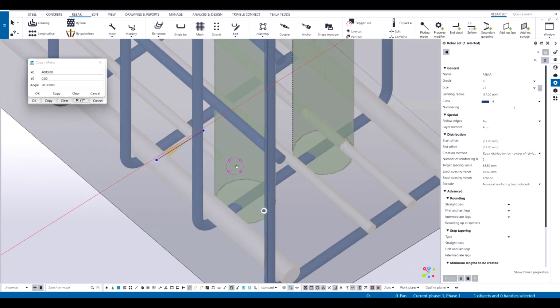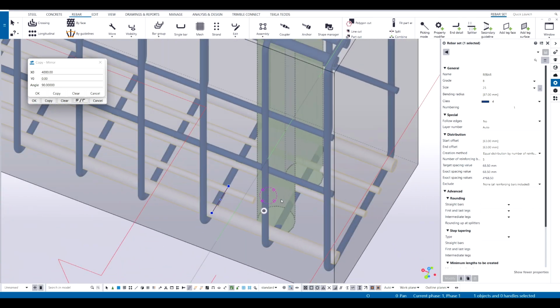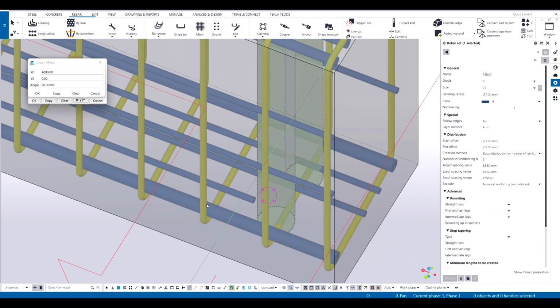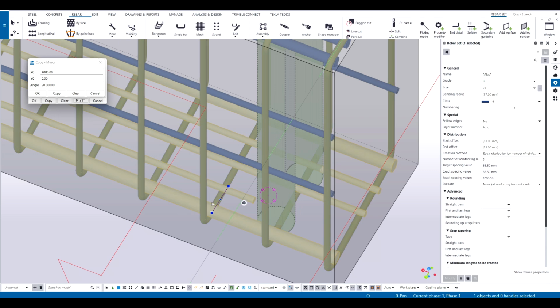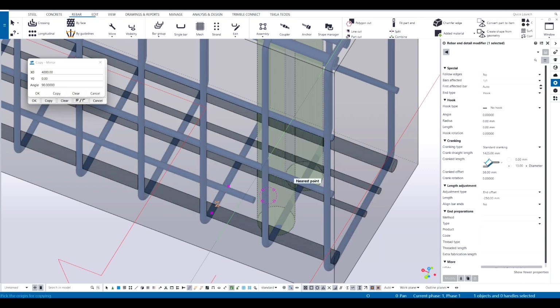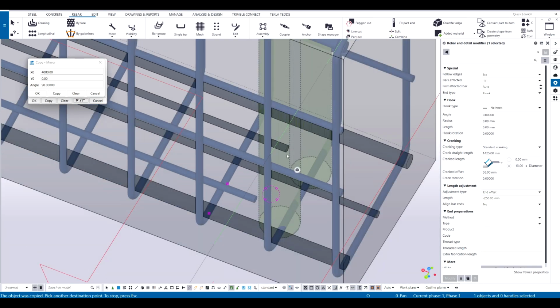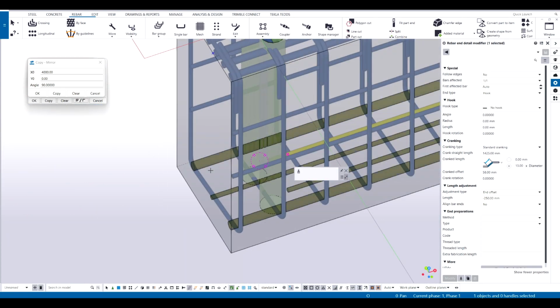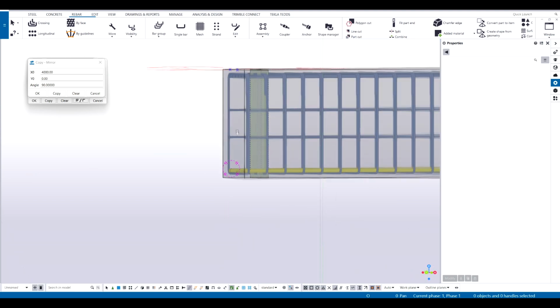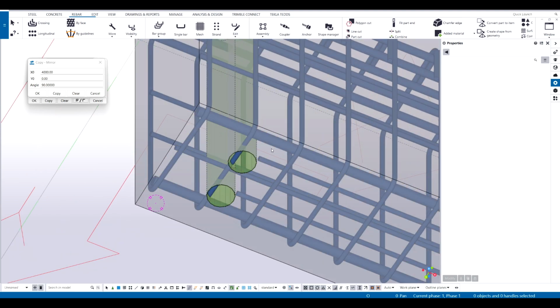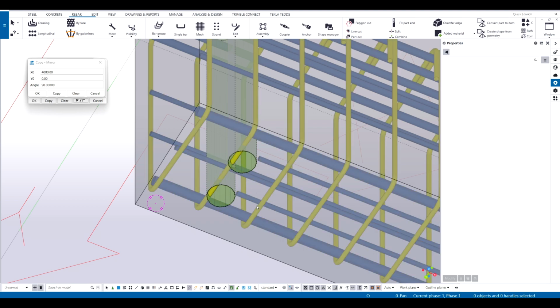So basically just Control C, selected this end here. Sorry, oopsies. Select this again. Select this. Control C. Now it's on my origin, and this is my destination. And you see that bar got shortened over there. So now I have 3 different lengths of bars. Just think of this. This is H25, 2 H12 in the middle, and then 2 H12s that are trimmed down.